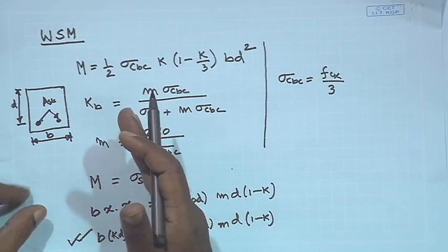So, that is why I am telling you that working stress method whatever given in IRC 21 or IS 456, or limit state method exclusively for IS 456, or the simplified method with the rectangular block, whenever we are going for say IRC 112, you will find the expression remains same, only a few parameters you are going to change, and from there you can find out how much is actually changing in your say depth of the beam or your say reinforcement.